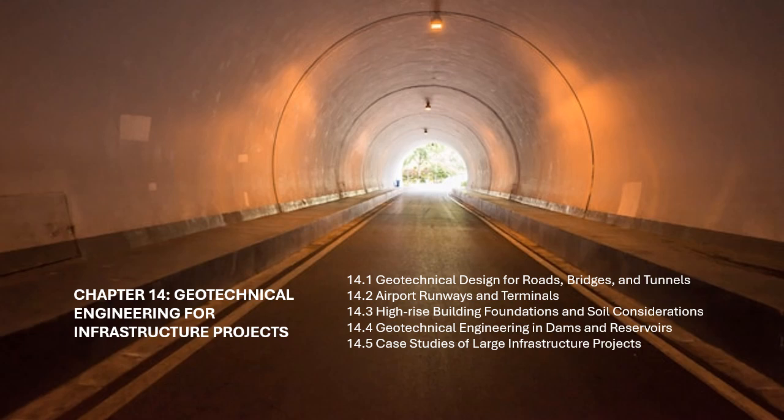This test is used to assess the soil's resistance to penetration and provide information about the soil's density and strength. It is particularly useful for determining soil stiffness and providing an estimate of the load-bearing capacity of the soil. Cone penetration test, CPT. The CPT provides continuous data about soil resistance, helping to define the soil profile more accurately. This test is used to assess the stratigraphy of the soil and to evaluate its ability to support heavy loads.